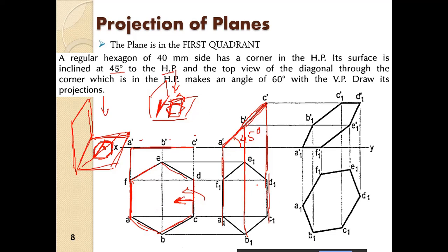And then to get the corresponding points from this hexagon, we draw from point F, we project it up to this point, up to F. All right, again from D, it is the same, it is lying on the same projector. So ultimately D is projected to this point. If it is rotated, we will have to consider D to D1, F to F1.